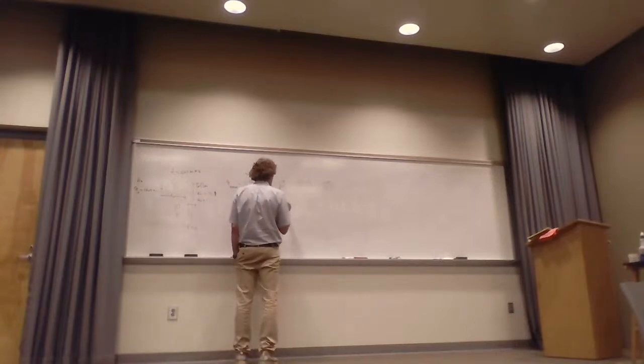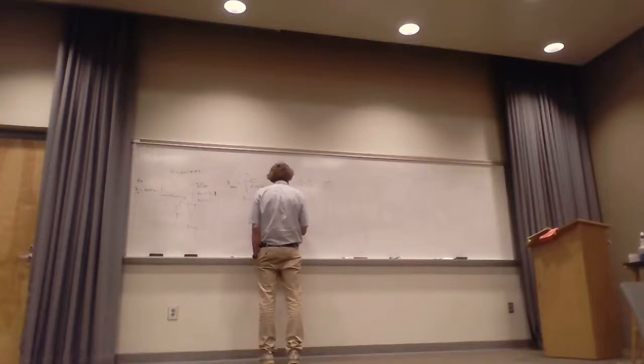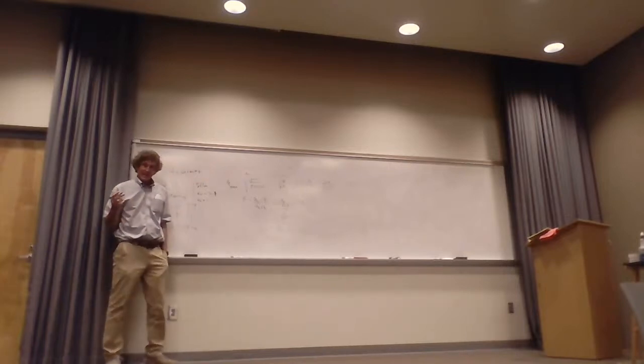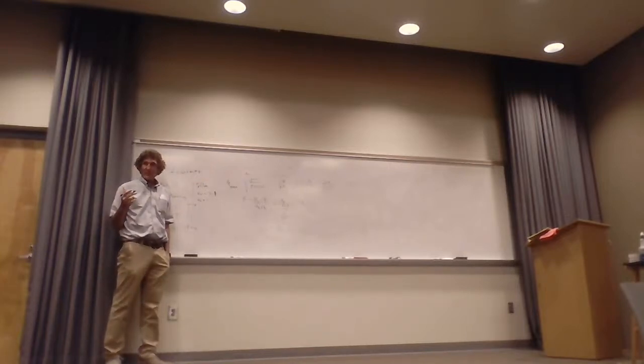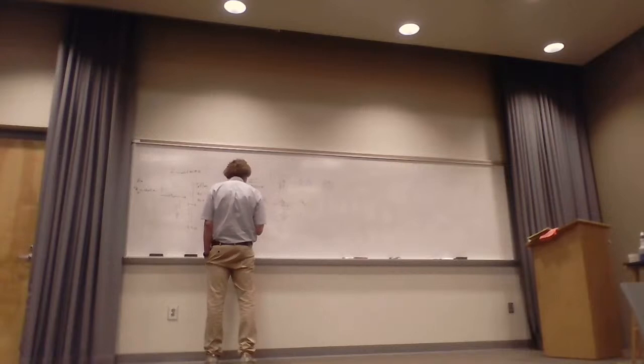So I can put eta Teflon as eta naught over the square root of 2.1, minus eta 1, which is eta naught, over eta naught over the square root of 2.1, plus eta naught. The reason I left the eta naught there is because I know they're going to cancel top and bottom, so I don't have to worry about it. You all follow me? And then I know the transmission coefficient. We'll calculate that in a second.